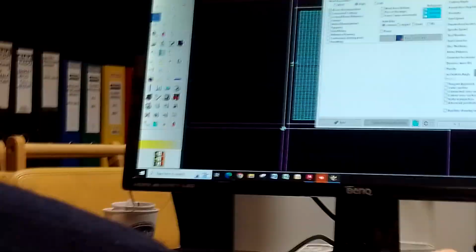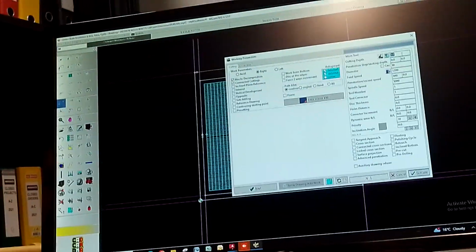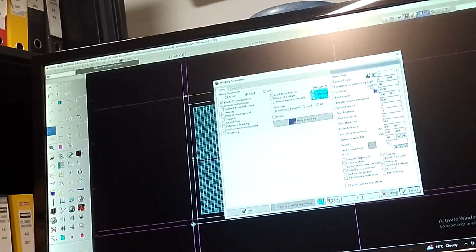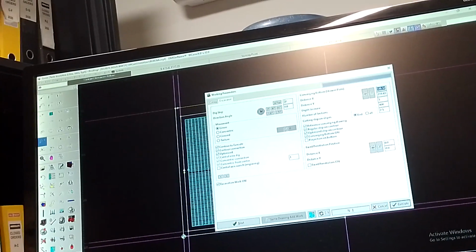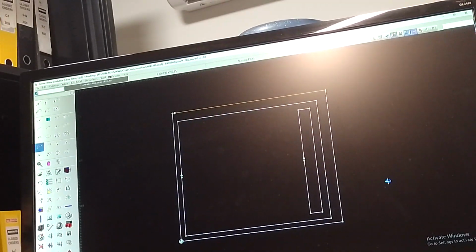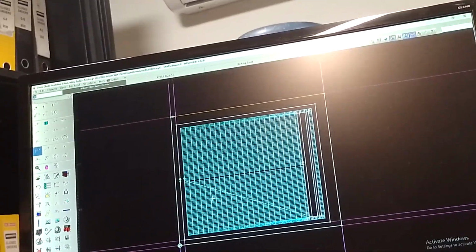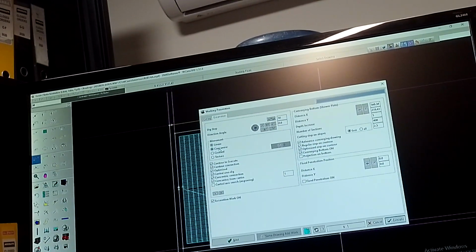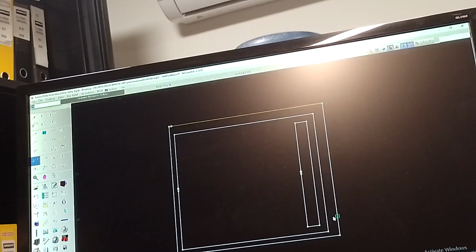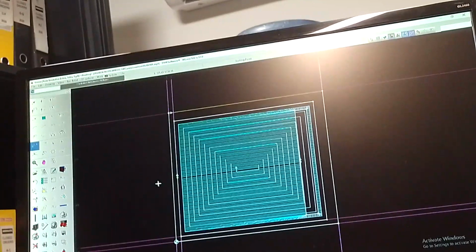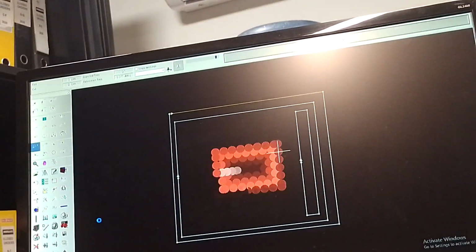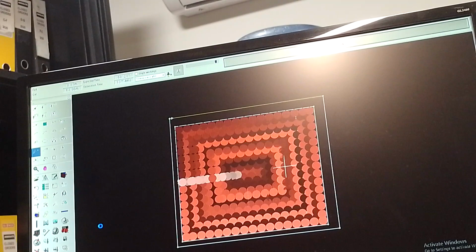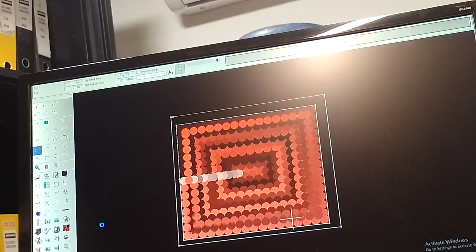So put here 10 millimeter. Here you put 2 millimeter, for example. Okay. In this case, it's correct to put 30 here, because it has to be done. But in this case, it should be better to use concentric movement for the excavation. One step, 2 millimeter, second step, third step, fourth step, 5 step, and then sharp plate.